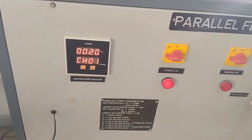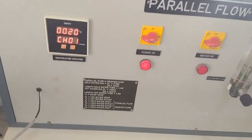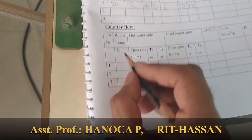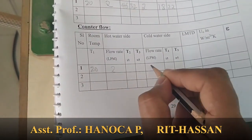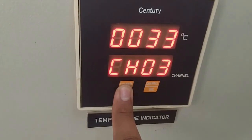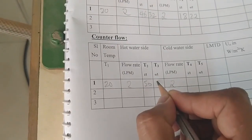Okay, around 10 minutes I left out to get the steady state condition. Once again we will start taking the readings related to the counterflow heat exchanger. T1 will be the same, the room temperature for the counterflow, 20. Flow rate will be the same, I have not changed it for the hot water side as well as the cold water side. Now we will check it out. What about T2 and T3? T2 is 50 and T3 is 33.